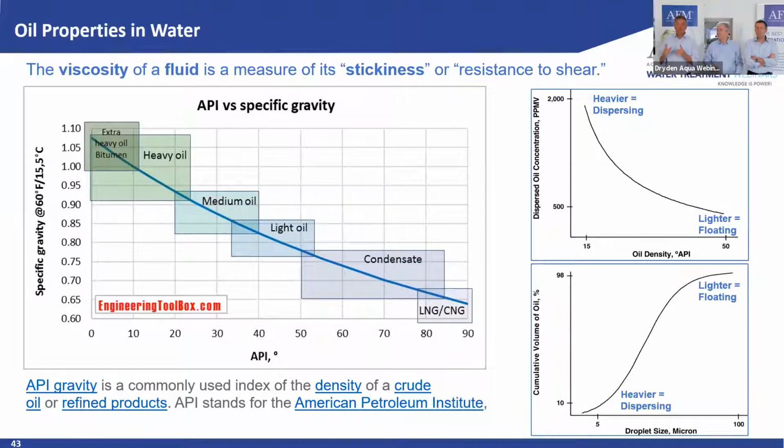But we talked about this, filtration is a process of holding them back, and to release them by backwashing, the more difficult it is to backwash. Exactly, because of the heavier oil. That's right, perfect, yes. Just to mention as a conclusion, heavier dispersed oils generate a lot of very small, fine particles, which we need to remove by filtration.